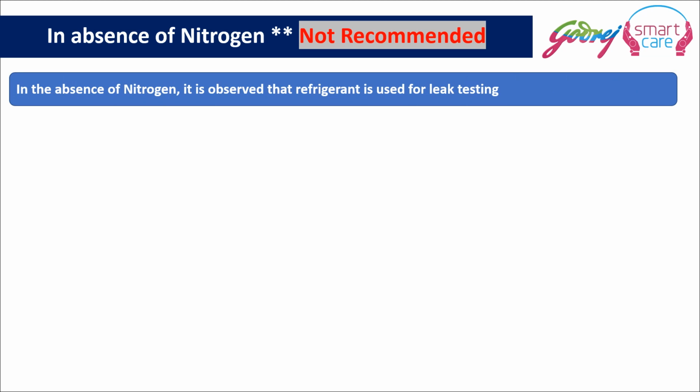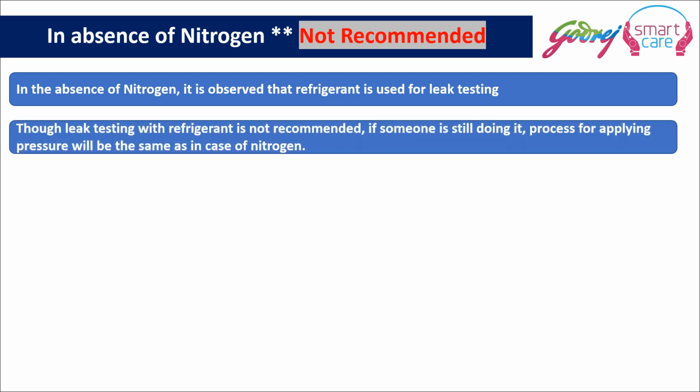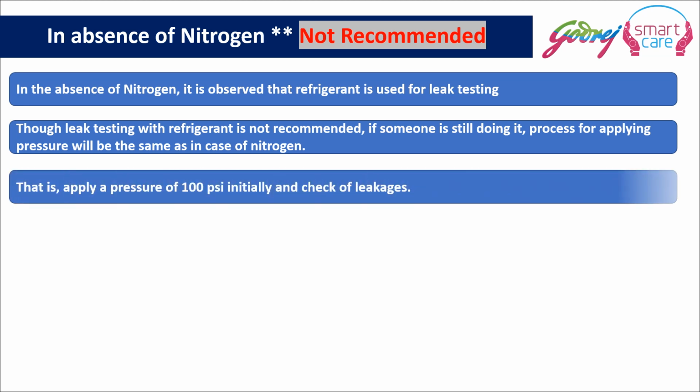In the absence of nitrogen, it is observed that the refrigerant is used for leak testing. Though leak testing with refrigerant is not recommended, if someone is still doing it, the process for applying pressure will be the same as in case of nitrogen.